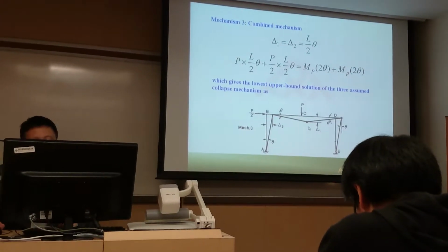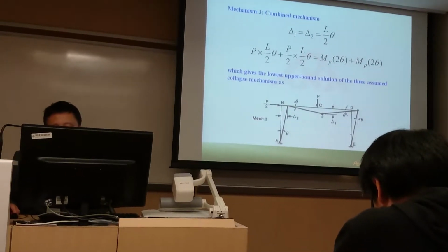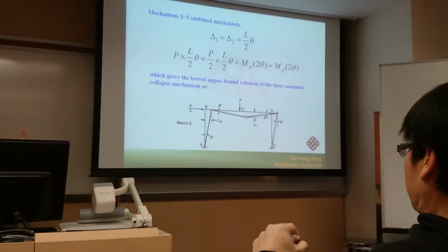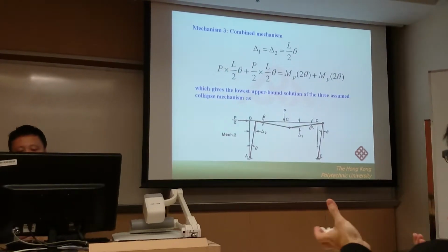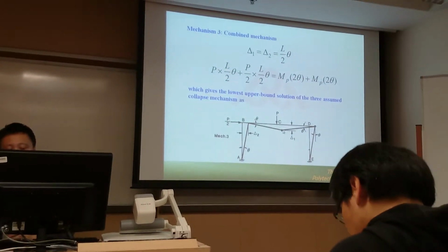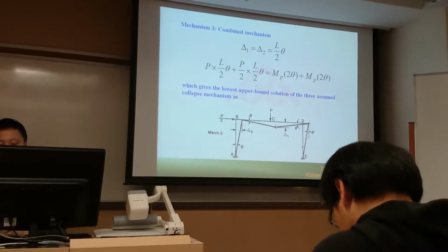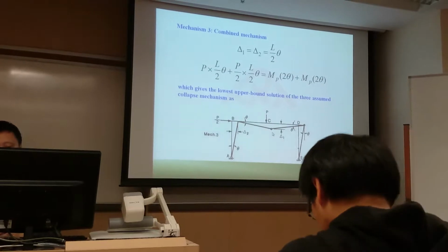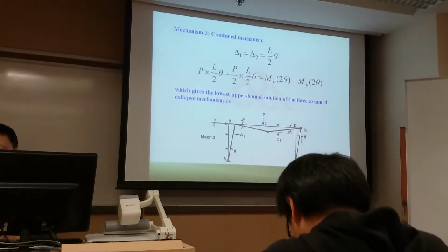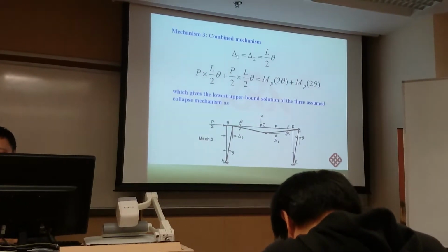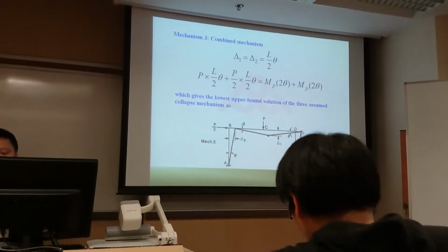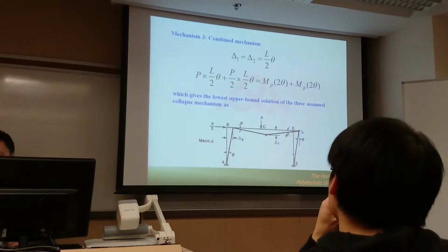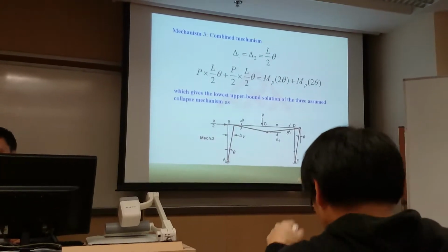Under the application of the force at point C, for this plastic hinge, the moment is a sagging moment, so the plastic moment at C is equal to positive MP. And the moment at point D makes a tension at the top of the section, so this is a hogging moment.